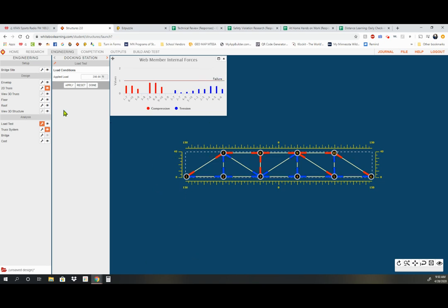So let's just check this out. Let me bump this up to 300. Okay, and we hit 300. I'm going to apply and watch everything change a little bit. Now, I'm still under threshold here, but my 7, 8, so this one to this one, and my 8, 9, this one to this one, are taking way more compression pressure. That means it's going to break at some point in here at 300 newtons.